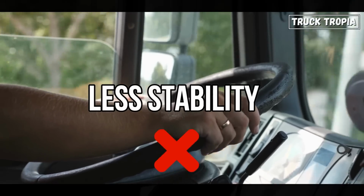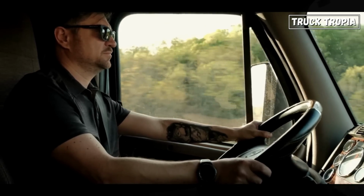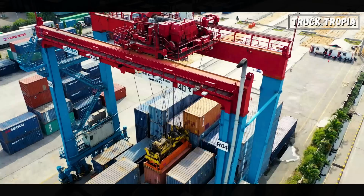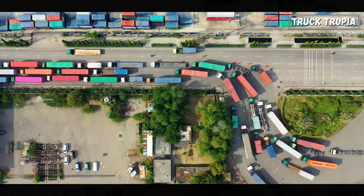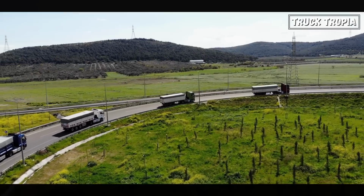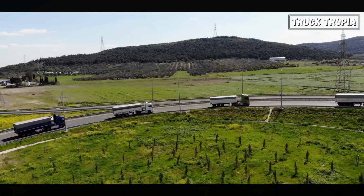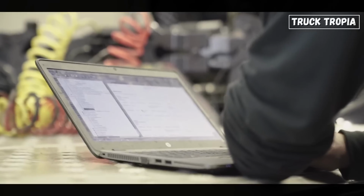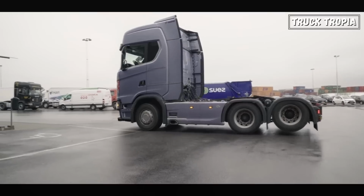Less stability. The lighter weight of the 6x2 configuration can make it more unstable in windy conditions and when turning at high speeds. Payload capacity. A 6x2 truck may have a lower payload capacity compared to a 6x4 configuration, depending on the country and the rules that apply. Durability. The 6x2 configuration may put additional strain on the rear tires and suspension, leading to faster wear and tear.